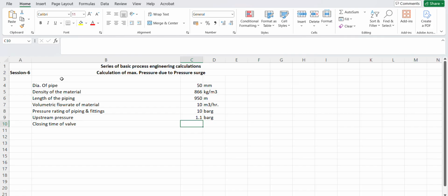And that is directly relevant to the pressure surge scenario. To avoid the pressure surge scenario, you sometimes have to go with higher size valves so that you will get more closing time than 3 seconds. But here we have considered the 50 line size, hence I am simply writing down the standard closing time as per the standard of the valve supplier.